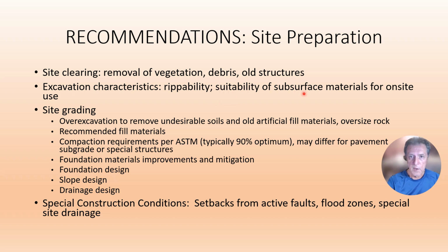And you have to say something about the suitability of the subsurface materials for on-site use, which means typically if you want to use on-site soils for fill, then those fill materials have to be suitable. They can't have too much clay or some other characteristic which is not appropriate.